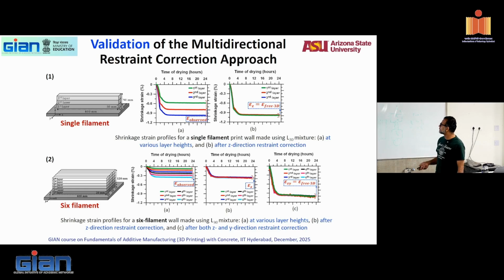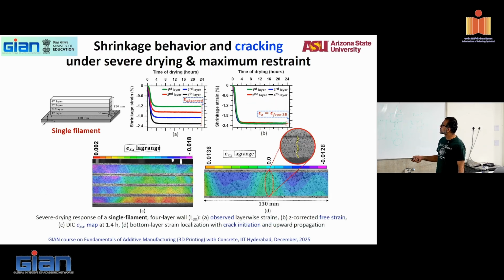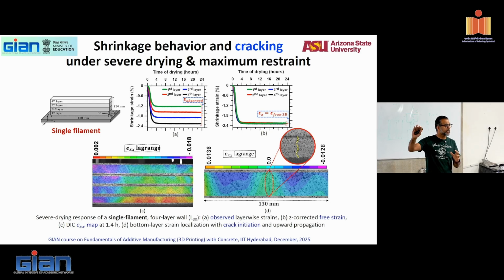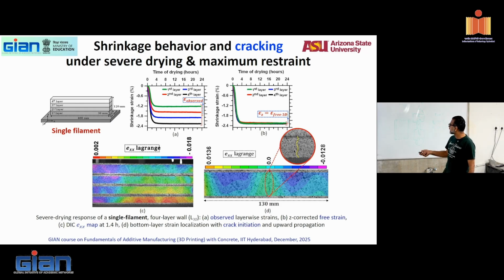So you can do a bunch of similar calculations, and you can also find out the elastic modulus of the material. Remember buildability, I showed you how to measure stiffness of a fresh material. Remember that? By carefully cutting a cylinder, applying an extremely slow strain rate and measuring the stiffness. So you can find stiffness development over time. If I have the restraint strain and the stiffness, can I not get the restraint stress? From the restraint stress and the tensile stress, can I not know if it'll crack or not? Right? So here is when our actual specimen is cracking under shrinkage.